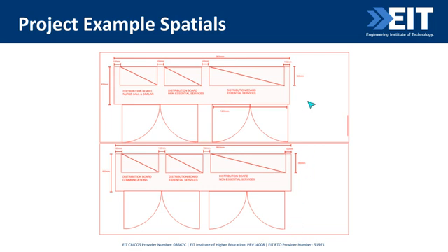So here's an example of a distribution board cupboard. This one has a 2-tier or a 1200 wide distribution board, as well as 2 600 wide distribution boards. You can see there's 100 mil between each one. Our board is typically about 300 deep, so we tend to allow a 600 to 800 deep cupboard. And then the last check is make sure your doors are wide enough so that when they're open, you can fully access your distribution board and it's not tucked in behind a corner.